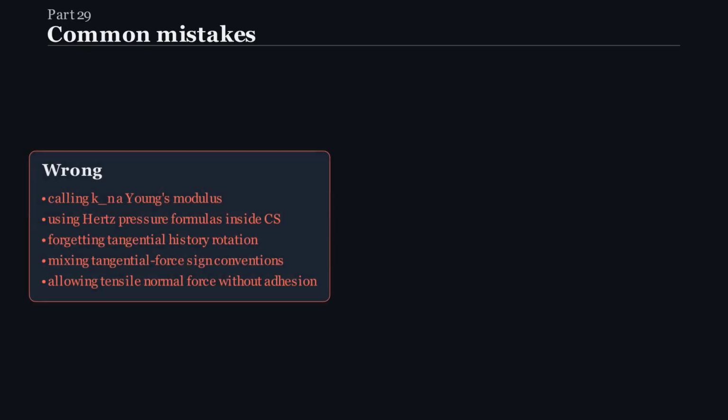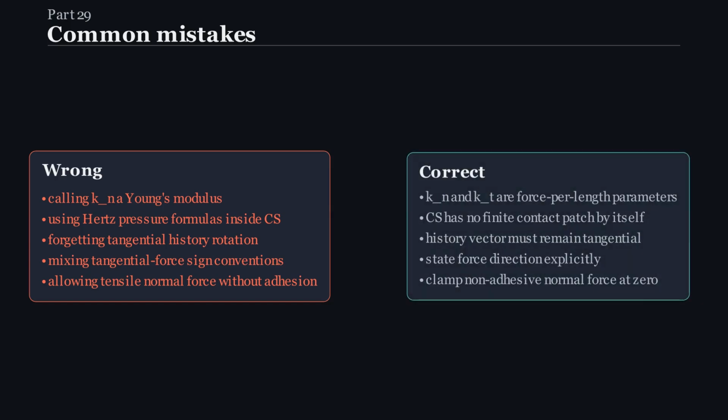The common errors are not cosmetic. They change the physics. The stiffnesses are not continuum moduli. Hertz pressure formulas do not belong inside a pure Cundall-Strack contact. Tangential history must be kept in the current contact plane. The force sign convention must be fixed before equations are written.